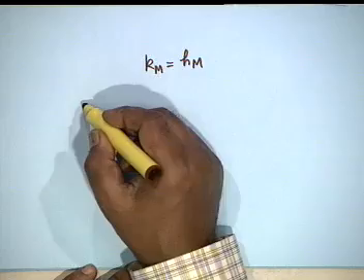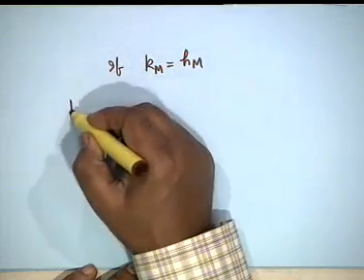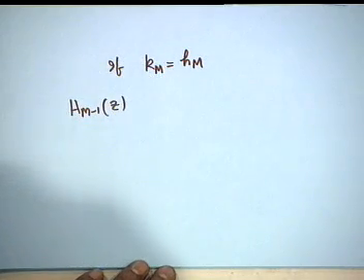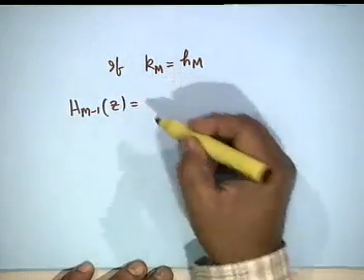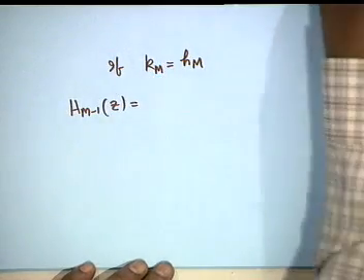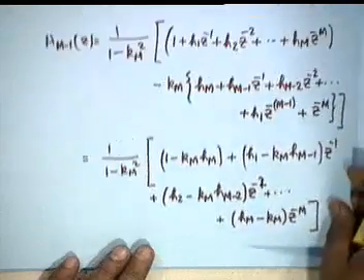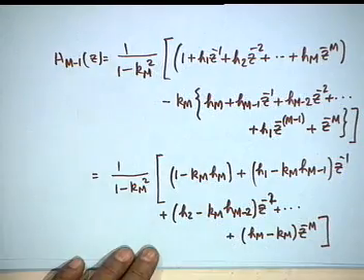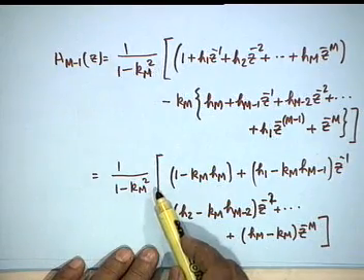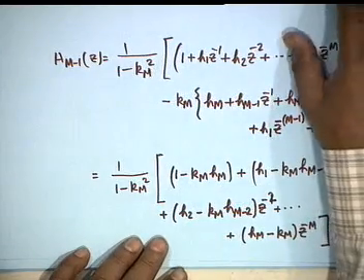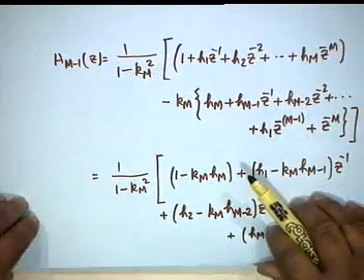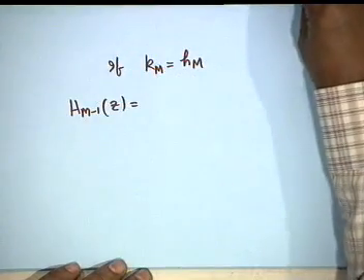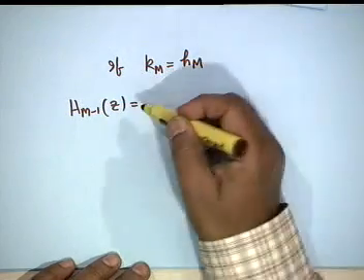and under this condition, if Km equal to Hm, then Hm minus 1 Z is of order capital M minus 1 and can be written with a constant term of 1 minus Km squared. So, constant term shall be 1. We are making progress. Hm minus 1 is of the same form as Hm, and therefore, iteration can be used.